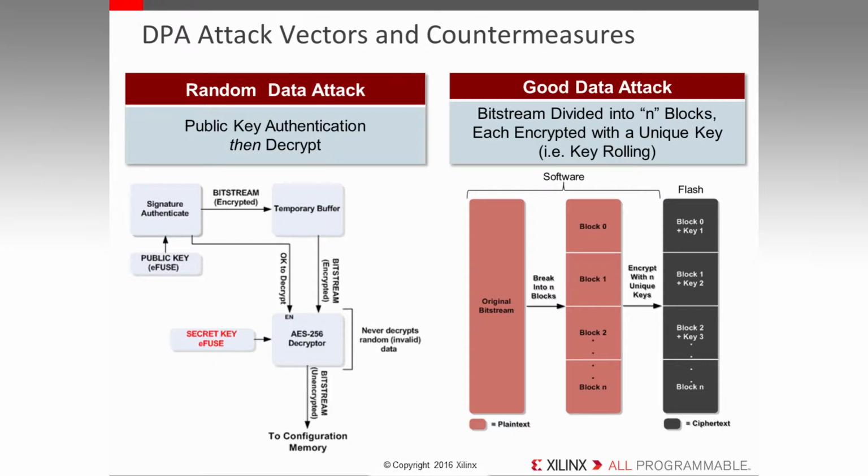There are a number of techniques to mitigate against DPA attack, such as using balanced circuits to minimize measurable swings in power or emission, or adding noise to raise the noise floor for measurements. The approach Xilinx has taken is to limit the amount of data an adversary can collect. This prevents the adversary from performing the needed analysis on the side channel information.